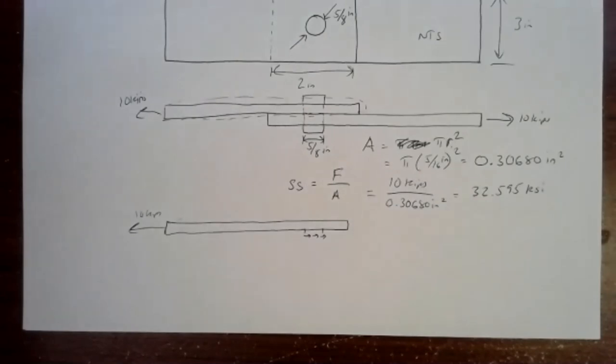Now, something that I'd be worried about in doing this kind of calculation is, is that shear stress safe? Is that going to be in the limits of the material I'm using? Now, if I know what this bolt is, then I can certainly ask that. On the other side of it, we can say, well, this is the shear stress I need. What material can I select that will be able to handle that? I'd want to pick a material that has an ultimate shear stress greater than 32.595 KSI so that it won't shear out in this particular application.